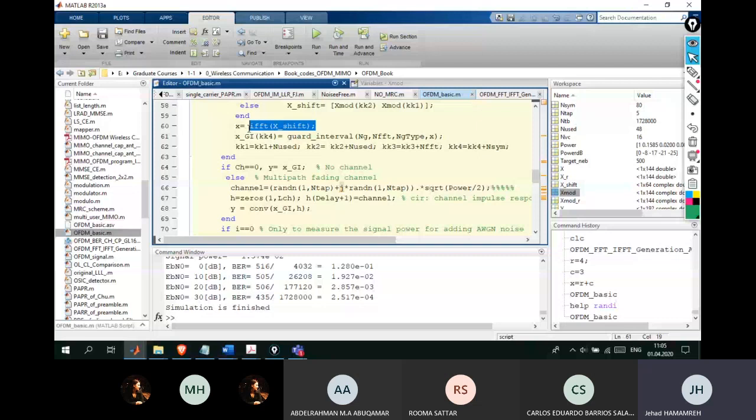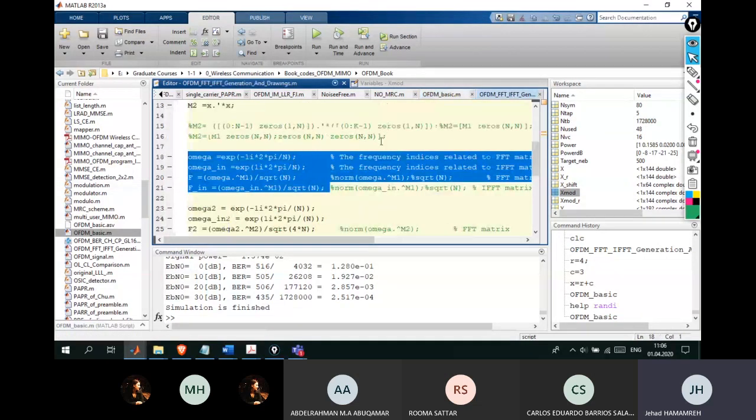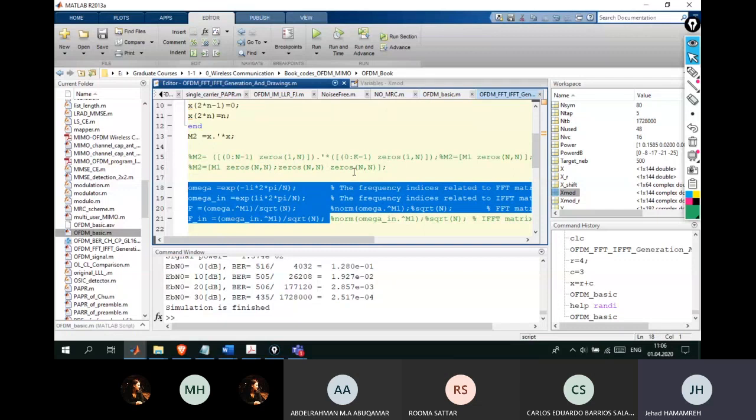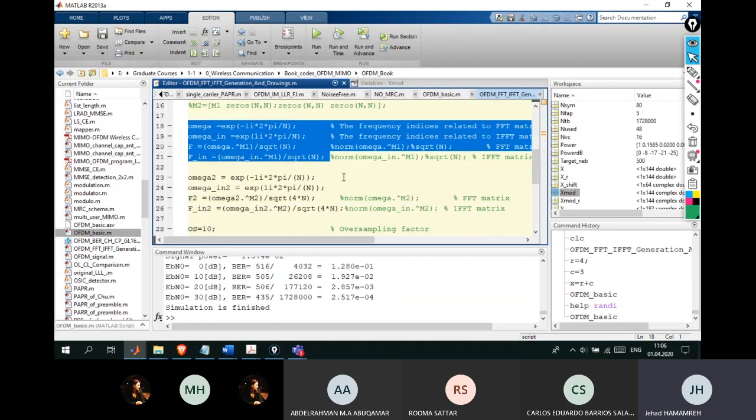The same point that I mentioned regarding the QAM mode. If this hides the technical details, the mathematical details, the knowledge from you, you just need to get rid of it if your contribution is related to building better waveforms with different shapes, different subcarrier spacing, different amplitude, whatsoever related to that. Now you will see the magic that we can do when we build the mathematical matrix of the IFFT process by ourselves and see how you can convert the math to physics practically.